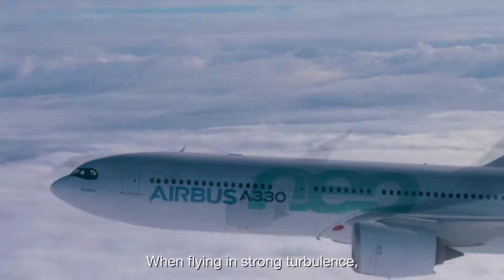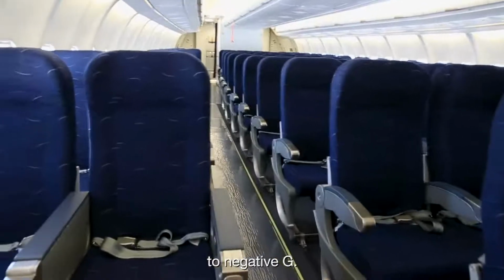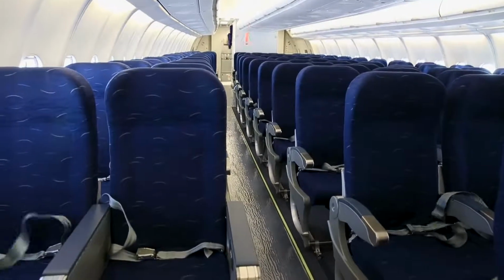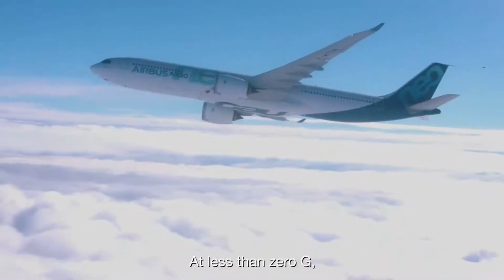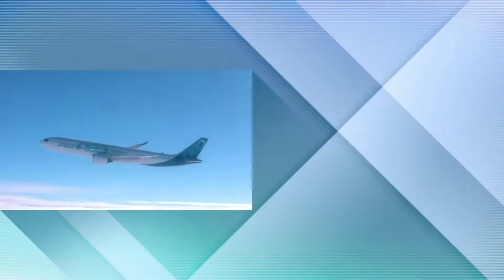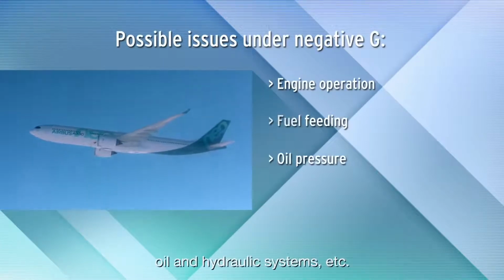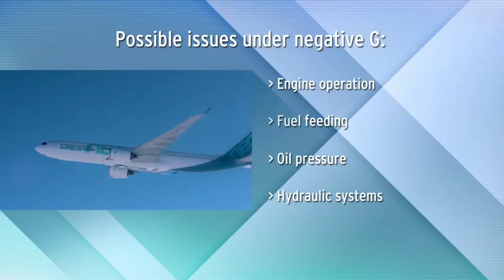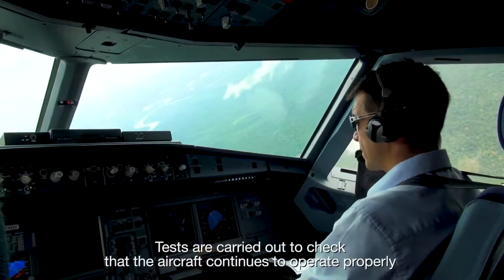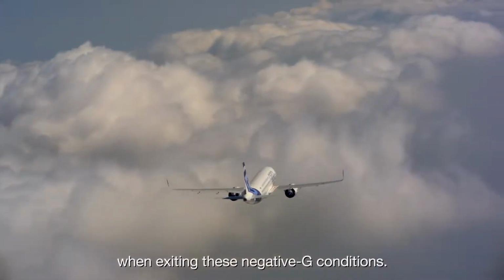When flying in strong turbulence, an airplane may be subjected for a very short period to negative G. At less than 0 G, the fluid flow may be disrupted in some circuits. There may be issues with engines operation, fuel feeding and transfer, oil and hydraulic systems, etc. Tests are carried out to check that the aircraft continues to operate properly and that everything returns to normal quickly when exiting these negative G conditions.